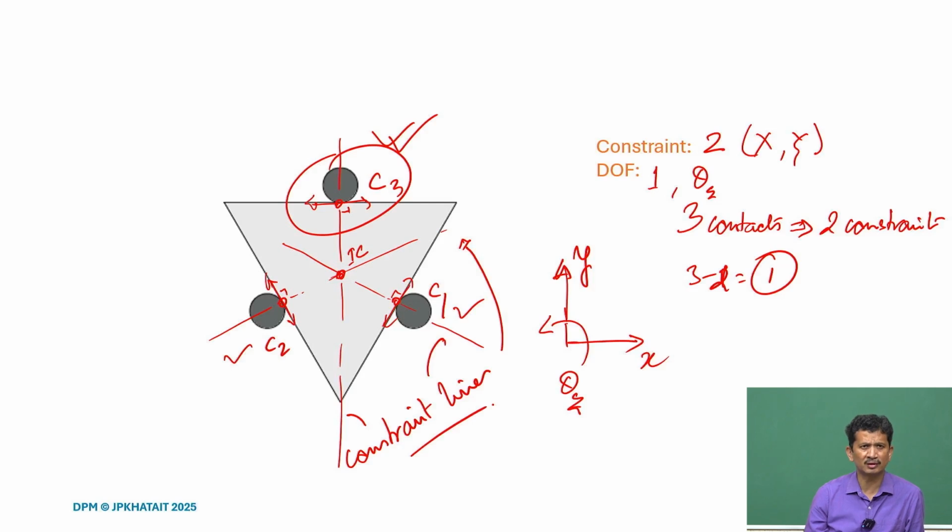So, it is an over constraint design. If we try to impose and use all the 3, what will happen? We need to have very high tolerance parts, or they will start fighting, because which two constraints should provide the 2 constraints, which is x and y translations.